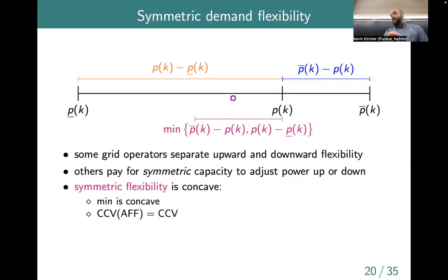Nominally, we'd like to keep the grid humming along at 60 hertz alternating current, which means if you look at the voltage waveform or the current waveform, you measure it on the grid, it's doing 60 cycles per second in roughly a sine wave, right? In Europe and Asia, it's typically 50 hertz, but US 60. So if supply and demand are perfectly in balance, then that frequency stays at 60. But if supply and demand go out of balance a little bit, so say you have less supply than demand, then the frequency on the grid would begin to sag a little bit. And so it might go down to 59.9 rather than 60.